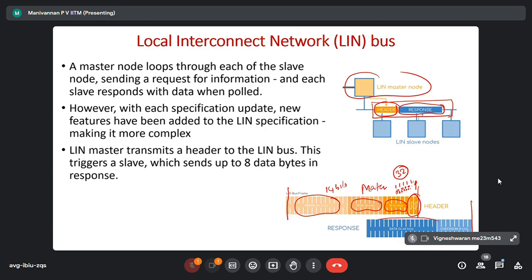This is the data: left window, right window. For example, there are 4 windows on the boot. That means the first message is whether the front left door, front right door, rear left door, rear right door is open. Each byte, if that byte is 0, you know that the door is open. If it is 1, then it is closed, like that.